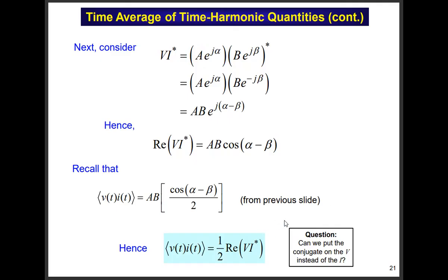Does that affect the imaginary part, by the way? Yeah, so you've got to be careful. The VARs would change. If you have passive sign convention going into a circuit, and you say VI is going to be the power going in, then you've got to be consistent. So then you want to put the conjugate here to get the VARs right.